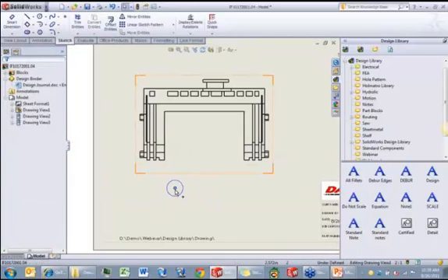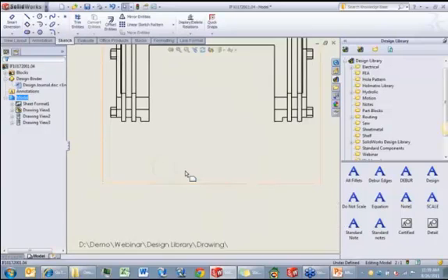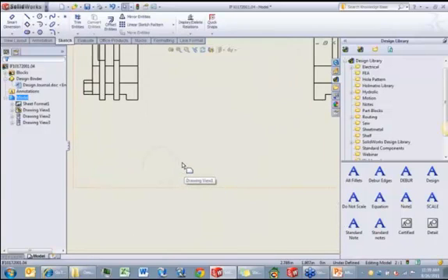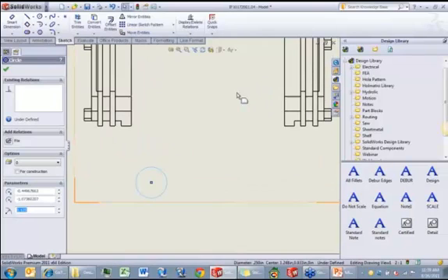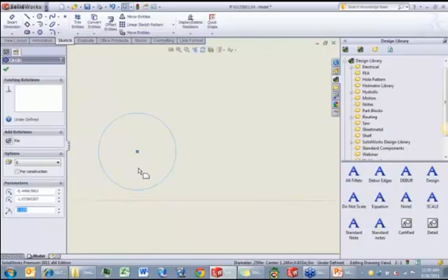In fact, I'll drag that down just a little bit. Now, one of the things I really want to point out is this block that I'm creating is going to take custom property information from the view that it's going to be connected to. So it's very important, in my case, that I create this block inside of another view. And you'll see why when I use it later.